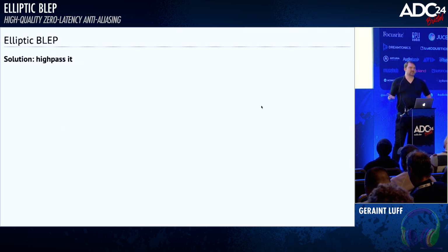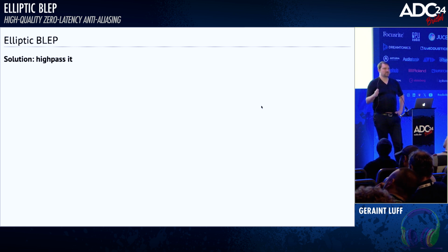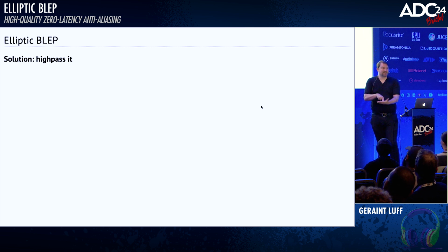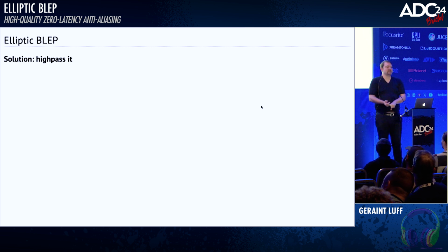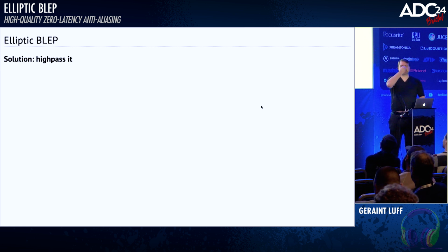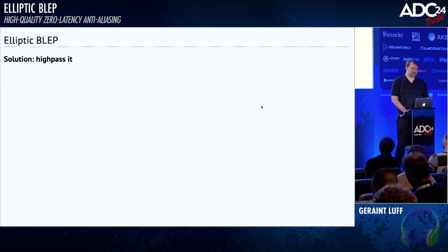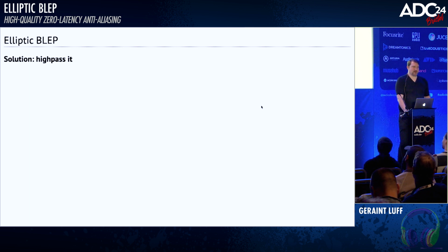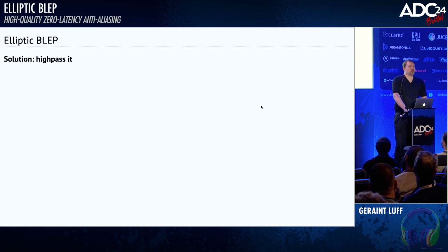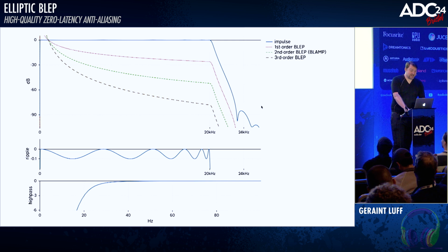If you apply any high-pass, then it will have a 0 amplitude response at frequency 0. If you apply a Butterworth high-pass, for example, a high-order one has repeated zeros, lots of zeros stacked on top of each other at 0 hertz. So it's very 0 at 0 hertz. As engineers and not mathematicians, we are allowed to play fast and loose with infinity. But here we have the idea of some things being more infinite and more 0 than others when you're talking about zero-pole cancellation. So bear with me in this horrendous hand wave. It does work out when you go through the equations, but you can also muddle through with intuition with enough practice. But this works, right?